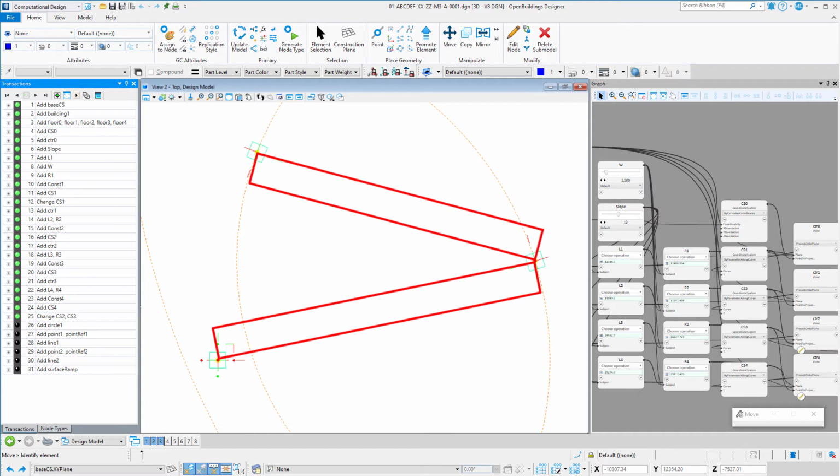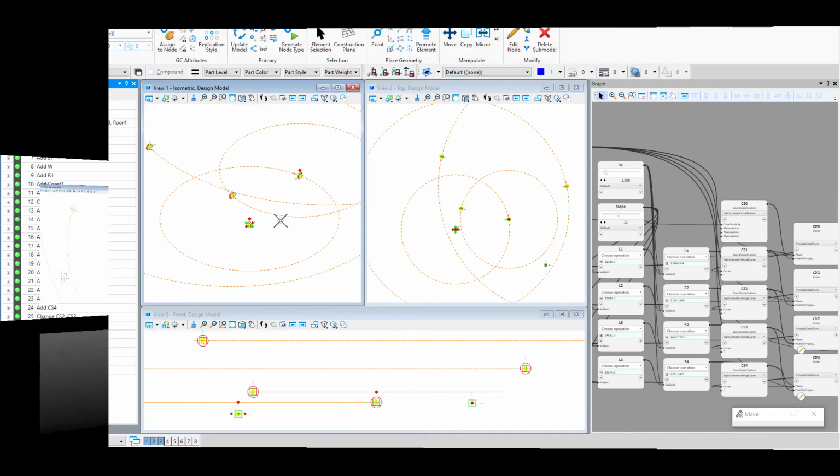So, as I discovered, this is not as simple as drawing a line string between these points. I need to create line strings that go from the point to the outer or inner edge of the ramp, defined by the next point and the ramp width. Since the angles between the ramps are not necessarily known and need to be free to move, this proved to be a little bit tricky. But again, I was able to use circles to define the width of the ramp, and then draw lines to the tangent points on the circles, giving me rectangular ramps with the correct width and length. So let's take a look.